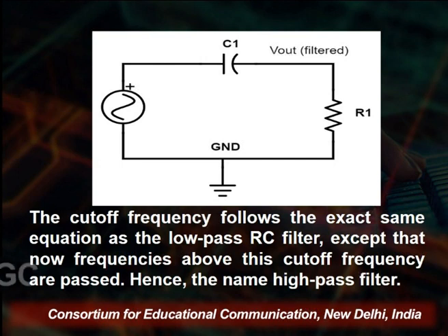So, the cutoff frequency follows the exact same equation as the low pass RC, except that now the frequencies above this cutoff frequency are passed, and hence the name, the high pass filter. Next, the low pass LC filter.